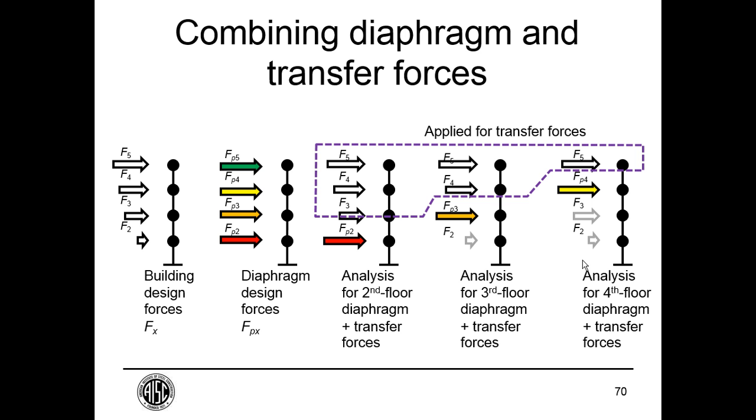And depending on your layout, your transfer forces may or may not be significant. You can look at your building analysis results and figure out how much transfer force there is. And there are different methods to use to manipulate the results to get this information out of a single analysis.